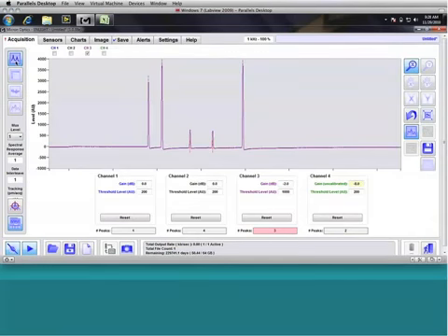One application where I've seen this is important is where a series of strain gauges undergo a large deflection, and as the strain increases, the peaks move, and as they move, they were decreasing. So during the life of the system, you would see these peaks decrease below the point of the threshold, and thus create this type of scenario in a real-world application.